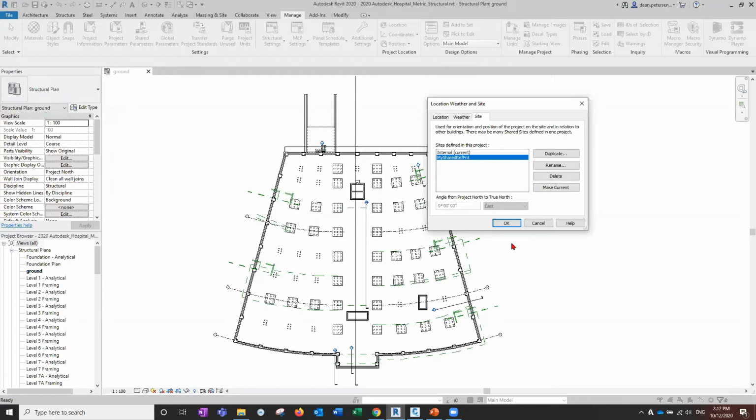The nice thing about this is that the Revit user still completely stays working in their own way of working. They don't need to use this coordinate system. It's only when they want to export things that they can switch to this one, do their exports, and everything goes into the survey coordinate system to make it match up, both in Civil 3D and, for instance, for using Navisworks as well. It will put it in a known coordinate system, or the exported coordinate system. So we make that current.